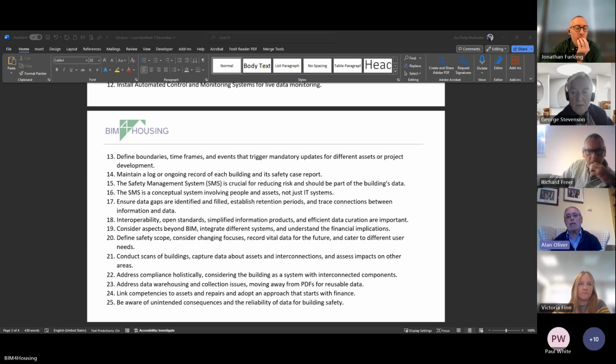The second thing I would say is that you're absolutely right that a brand new door might not be installed correctly. You've got to look at the complete golden thread of information, and just because you've got a brand new, fully certified, manufactured fire door, you can make a complete horlicks of installing it. And it's out there in the public domain where that's been happening on numerous occasions going back a long time.